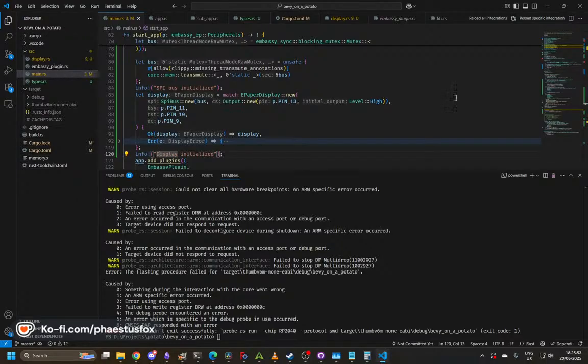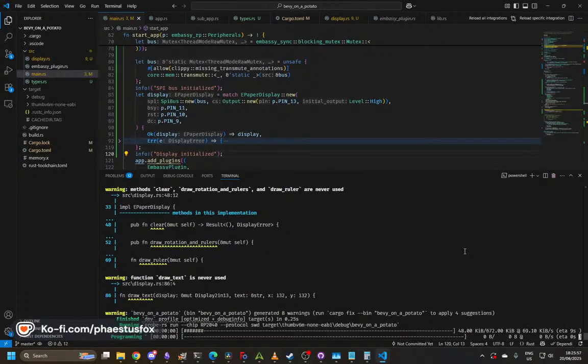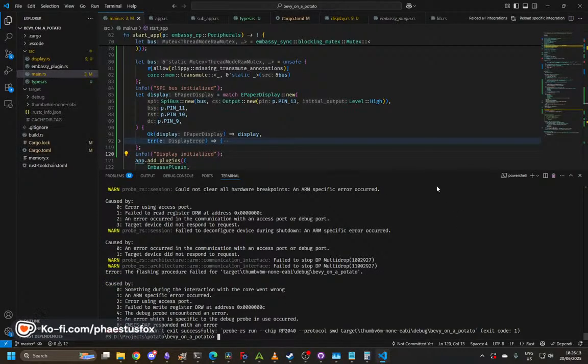So if we rerun that and actually get it to send the code, I can now use my multimeter again, because it was connected so that I could measure the amps, but obviously I can't measure the amps to stop running. So let's measure voltage, and let's work out, first off, have I just not plugged the display into power? That would be my most likely guess, that the voltage between here and here is not 3 volts.